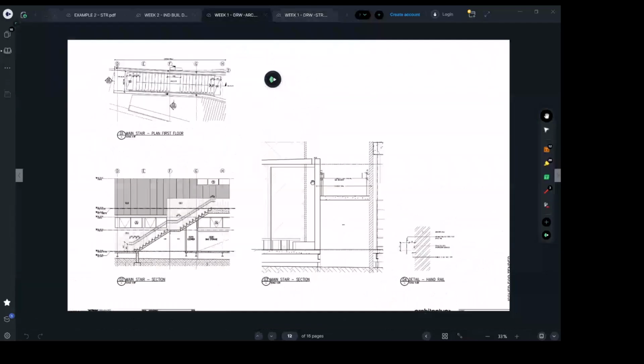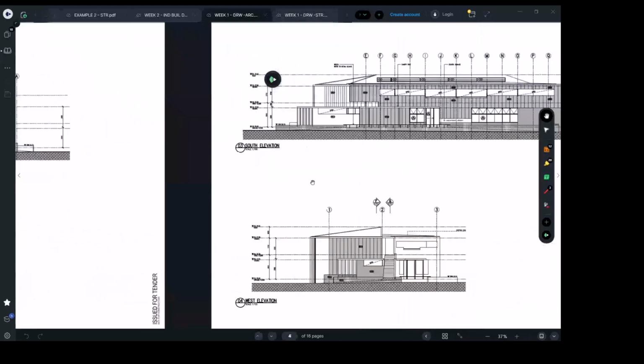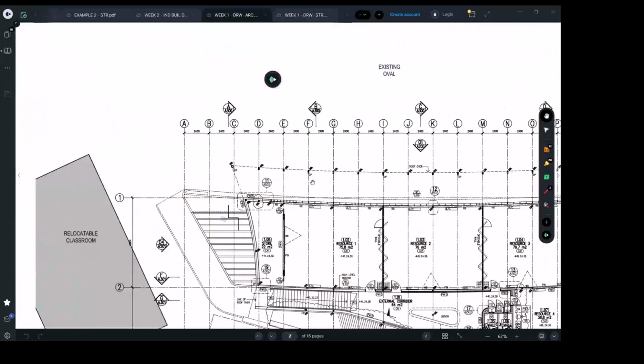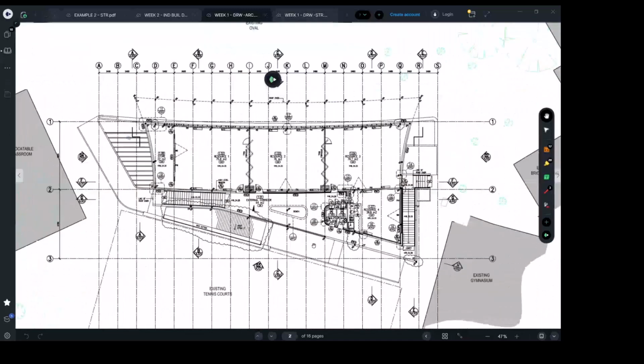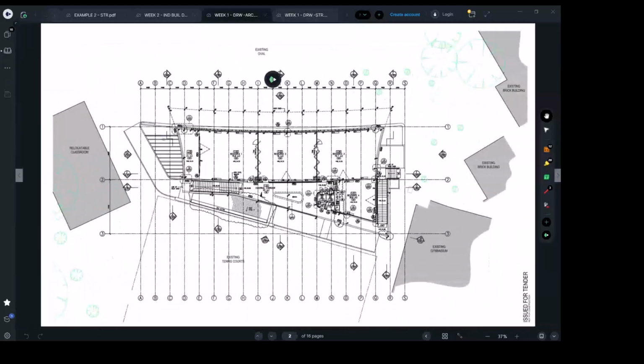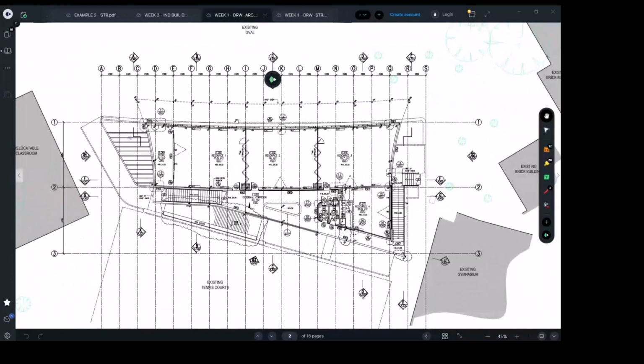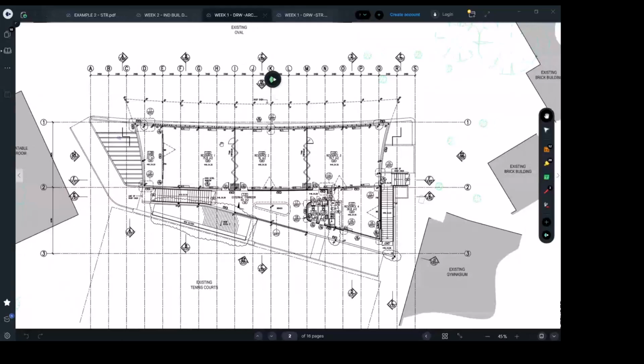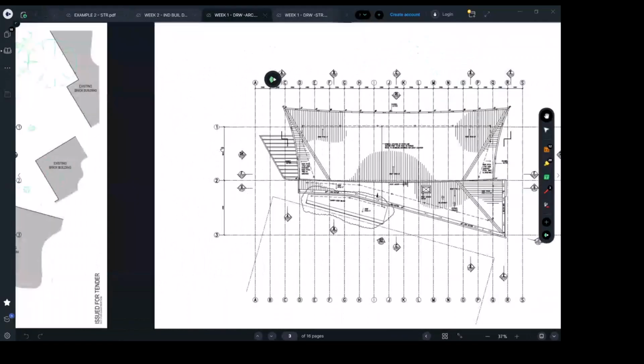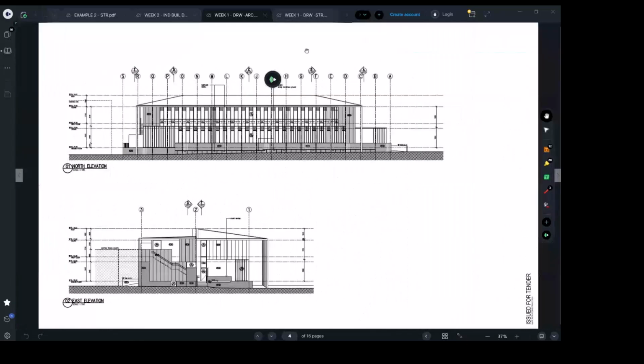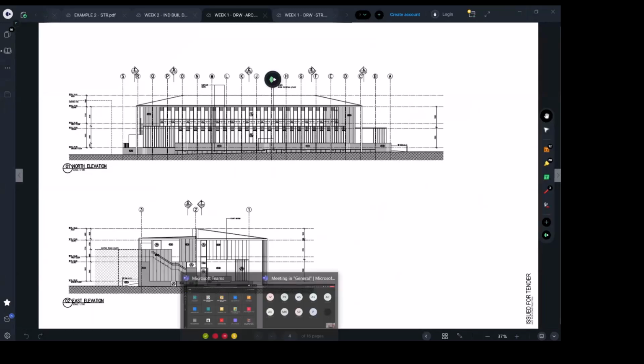Like if you go to the site plan, for example, it's the same project we're talking about. If we jump, maybe we didn't have a site plan here. Yeah, I can't see any services pipes located around here. So still, if not, that's where the discussions need to happen, just to make sure your footing won't be sitting on them. And also, given that you are the builder, you need to check that they are documented on the structural drawings as well, right?